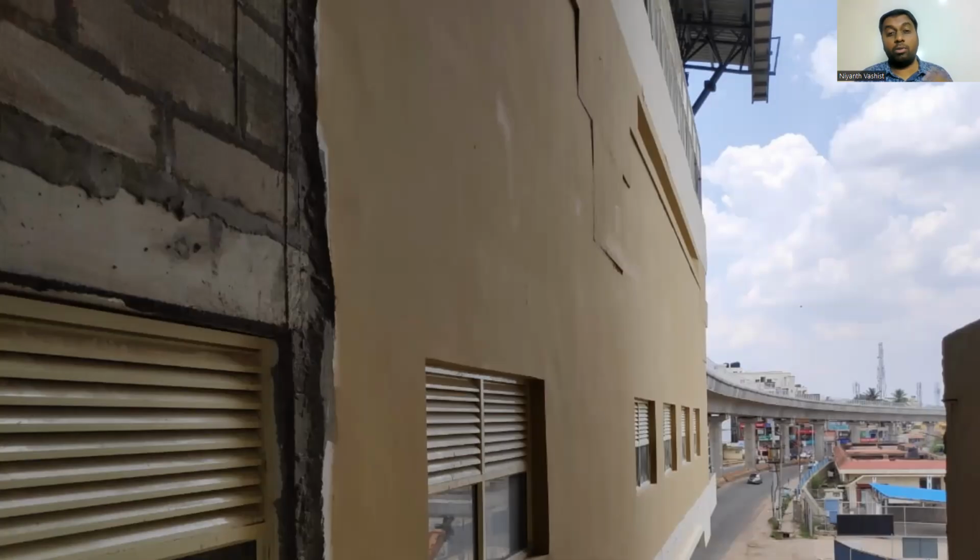According to the plan, we had to do multiple rooms. Again, one thing that we need to understand is just the slab is not enough. That is why we had a different treatment on top of the slab to make sure the vibration is absorbed properly. Because one thing is very important in a metro station, it has to absorb the vibration, because the metro will cause a lot of vibration. So just a normal slab is not enough.